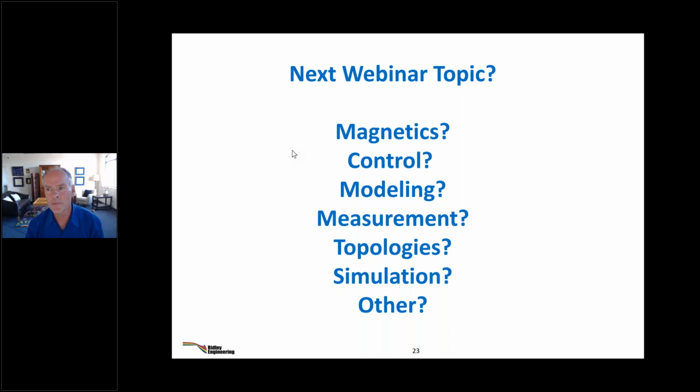Should you build an LLC? If you're in a hurry, no. I'm not even trying to answer whether this is the right topology to use. It is a topology to use. It is turning out to be the topology of choice for industry where you've got a pre-regulated input.